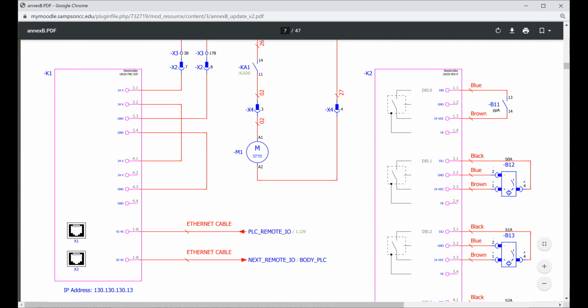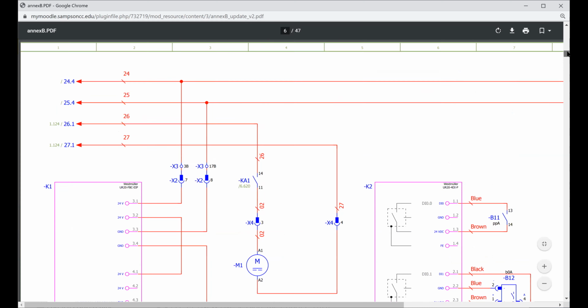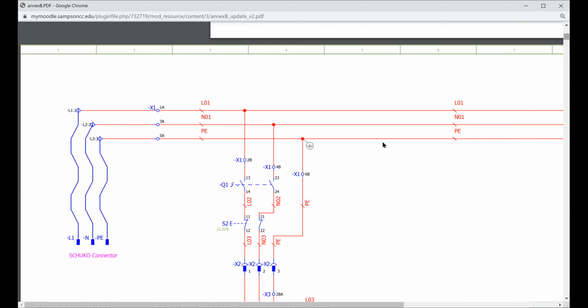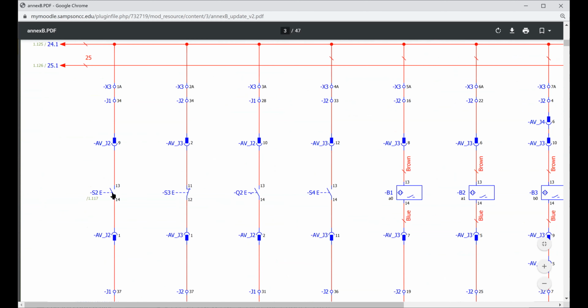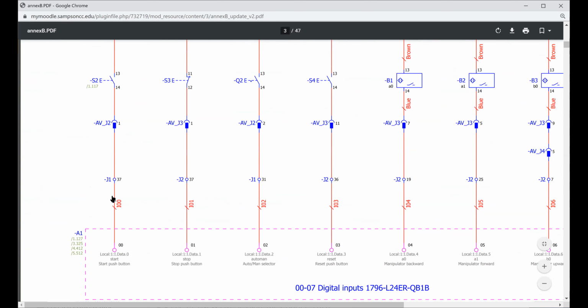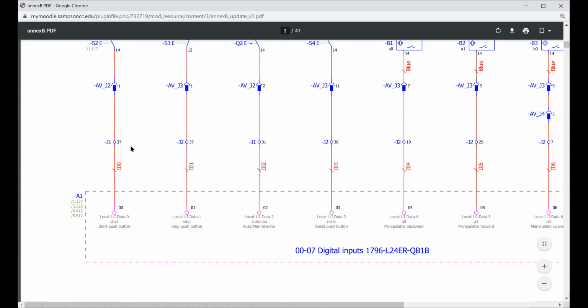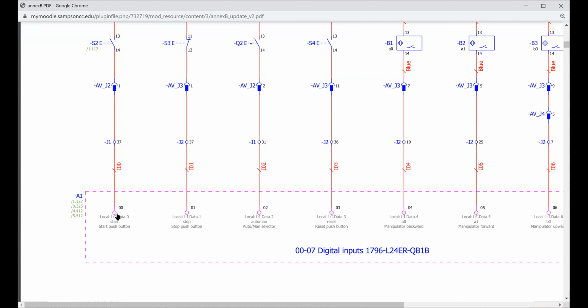That's when we begin to look at how you physically check things with a meter. So we will go in, say, right here where you've got a start button. We're going to let you see how to put a meter on this terminal and check from here to common and measure the input for the start button. When you press the start button, you'll check the DC volts coming in, and you'll start to learn how to check your buttons and how to check sensors whenever you're testing and troubleshooting, okay?